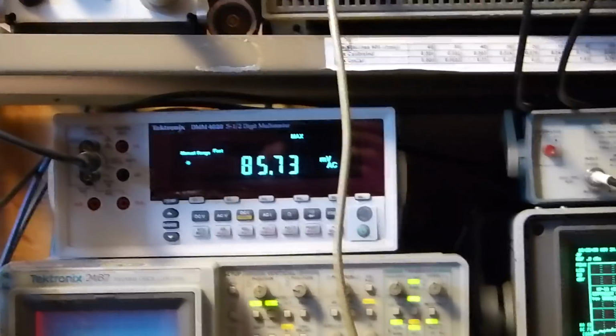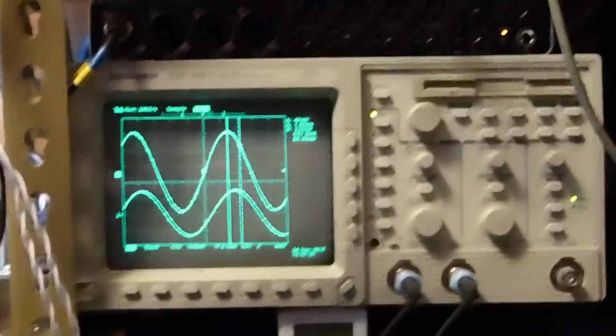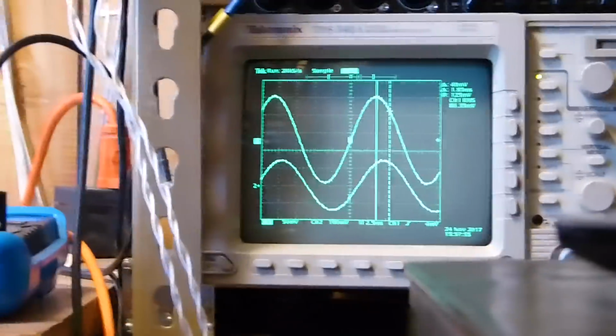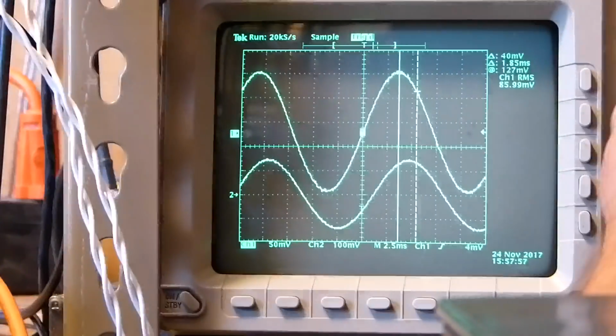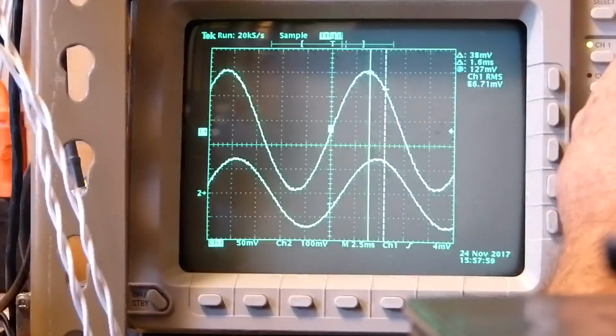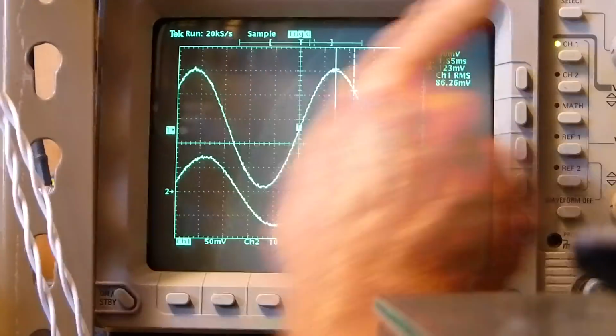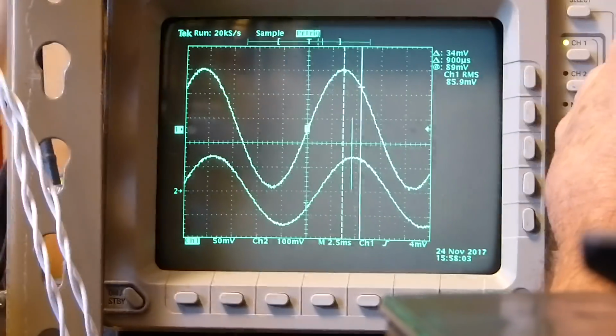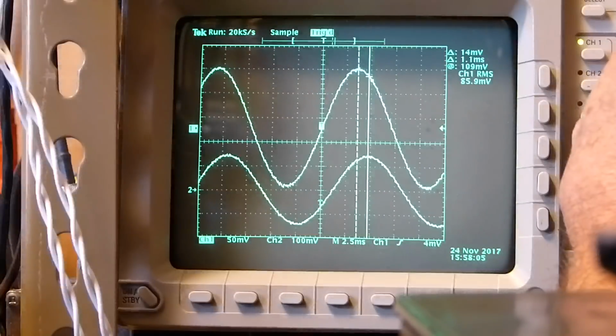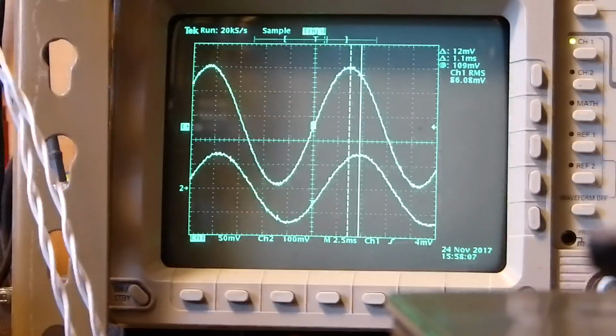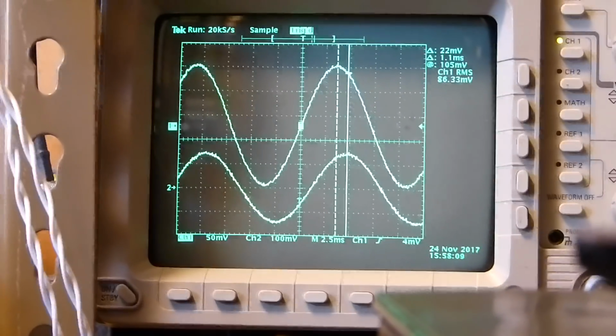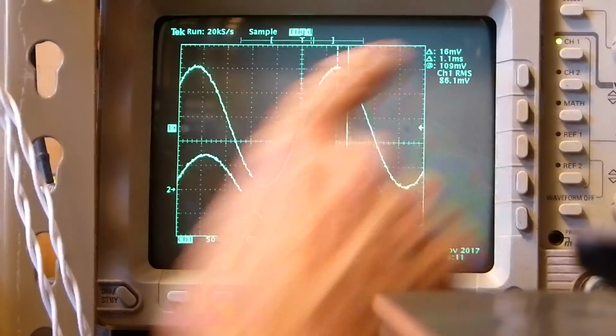And there's our voltage. Let's set this guy up down here. It's going to be very narrow. As the inductor gets larger, the phase shift gets less. Okay, this one is splitting the top one. And now we've got to split the bottom one. And this is probably about as high an inductor as you're going to want to measure. That's 1.1 milliseconds.